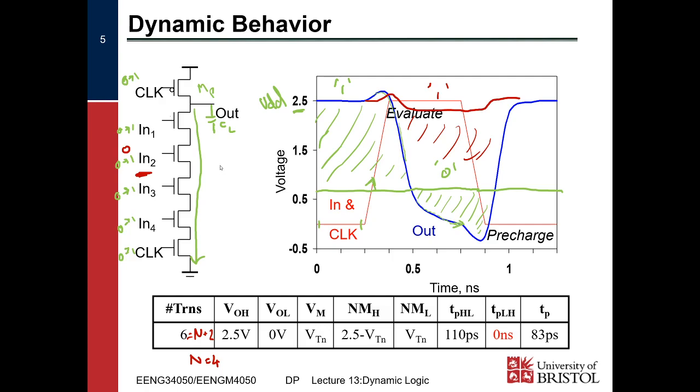So it combines the functionality of the sequential side and the combinational side in dynamic logic, so it's more efficient in the fact that we don't have to add D flip-flops if we don't want to, right? But obviously there are other issues with it. So in a sense, yes, but purely because dynamic logic is on its own sequential. D-type flip-flops are just another type of sequential logic, right?